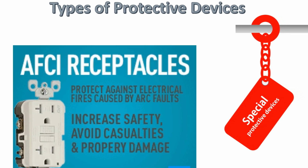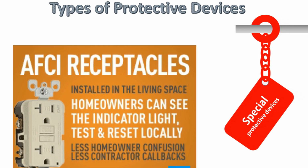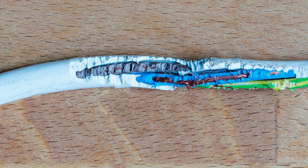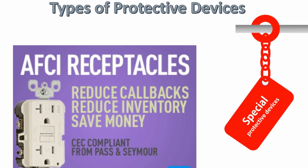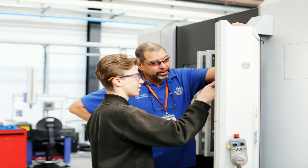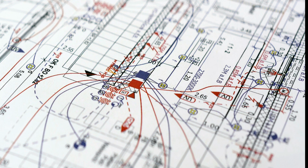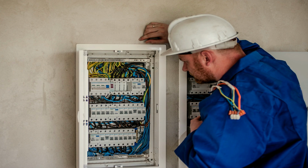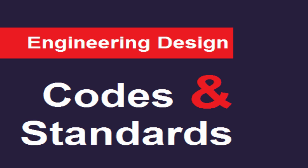The AFCI basically protects against arcing fault. Arcing fault can be caused by deteriorated cables. The AFCI are recommended to be incorporated for circuits feeding outlets in building rooms such as the bedroom, closets, etc. As an engineer, proper analysis of projects is thus required so as to be able to select appropriate protective devices for our project. And I will also recommend being familiar with the NEC principles.